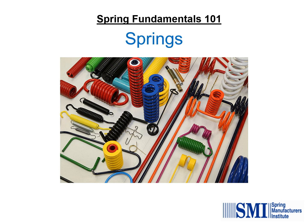This slide presents a colorful view of the different types of springs that we will discuss today. The photo is from the Myers Spring website. Springs are made in many types, shapes, and sizes ranging from delicate hairsprings for instrument meters to massive buffer springs for railroad equipment. The majority of this module discusses the relatively small springs that are cold wound from wire. Wire can be round wire, shaped wire, or flat strip. Chemical composition, mechanical properties, surface quality, availability, and cost are principal factors to be considered in selecting materials for springs.